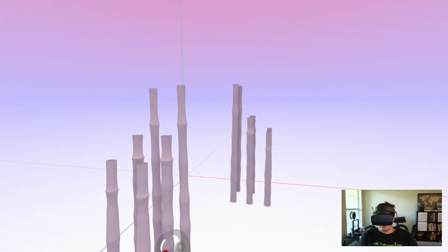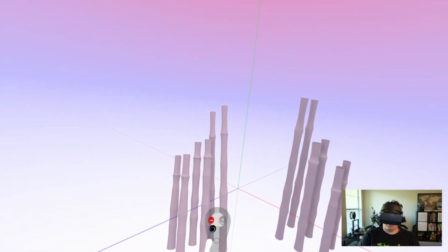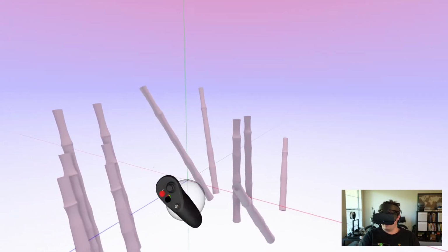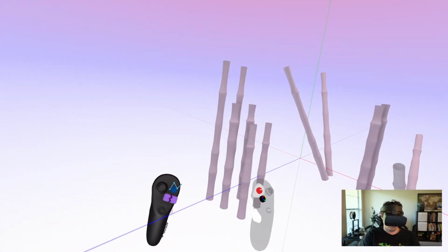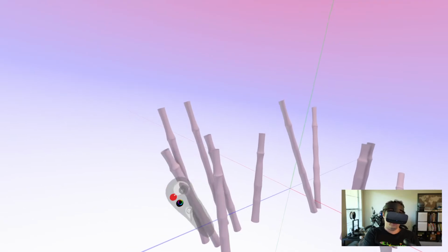Now, something to note is that when you do this, if the thing you're making a prefab had mirroring to it, like this is a mirrored thing right now, you'll see that this is just one big group. I can break this group by clicking the purple break button. These are all individual pieces.